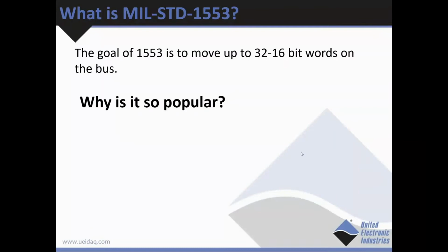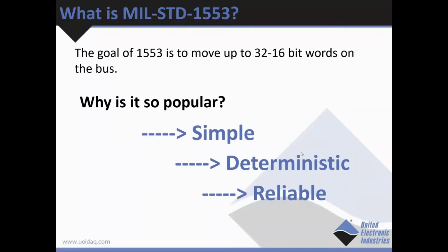The goal of 1553 is to move up to 32 16-bit words on the bus, but it's as simple as that. A military aircraft is run by a series of 16-bit words. So why is it so popular? It is simple, deterministic, and reliable.